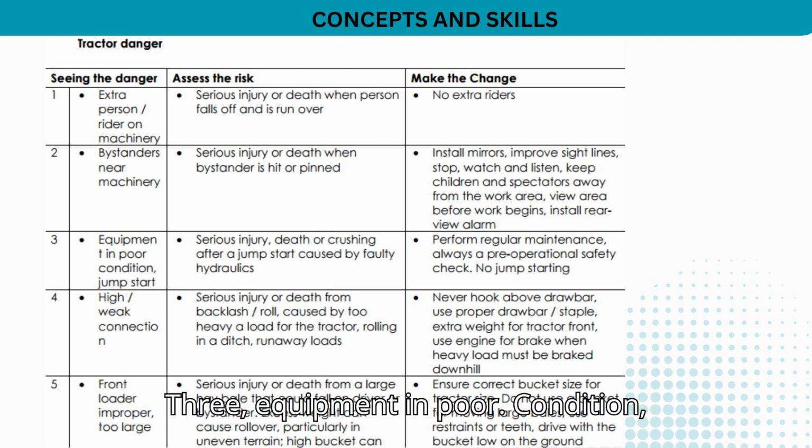3. Equipment in poor condition, jump start. Serious injury, death or crashing after a jump start caused by faulty hydraulics. Perform regular maintenance. Always do a pre-operational safety check. No jump starting.